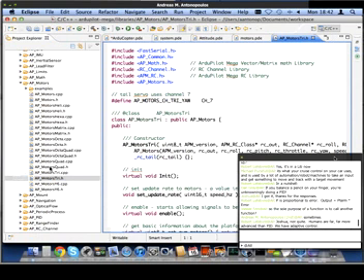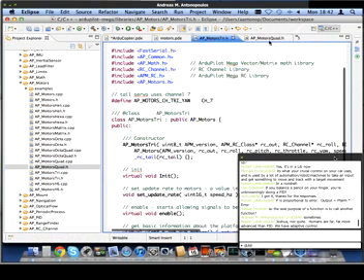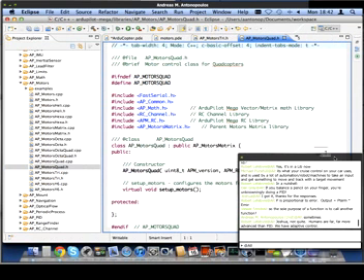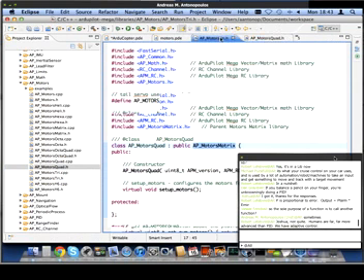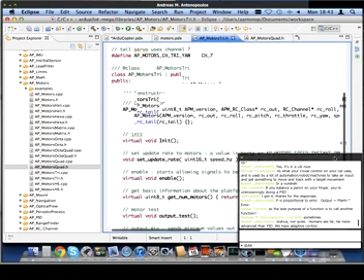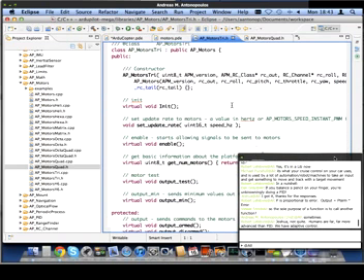So let's have just a quick look at the AP motors tri.h. Andres, can you pull that up? AP motors tri.h. Perhaps quad will be better because most of the people use quad. I could do that. It's a little bit more complicated, the quad one, but yeah, we could look at that one if you like. So yeah, the additional complexity with the AP motors quad and the hexa and the octa is that they in turn inherit from the AP motors matrix class.